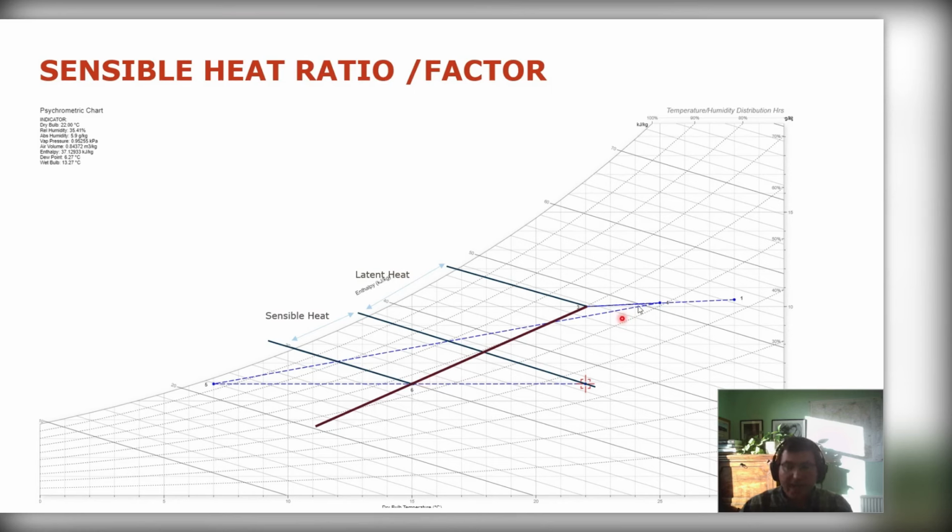That's the important thing. And that's what you can work out and graphically show in a psychrometric chart. And then you can play around with your figures and decide how you will achieve it specifically in your situation. So that's kind of the useful bit about it. Now, of course, to do this calculation, what you have to know is how much heat gain there is in the room and how much moisture is gained in the room. And that's the tricky bit sometimes. So that's something that you would need to work out based on your specific challenge. Those are the inputs that you need to have. But once you've got them, everything else you can work out using the psychrometric chart, because you fix the points and you calculate between them.